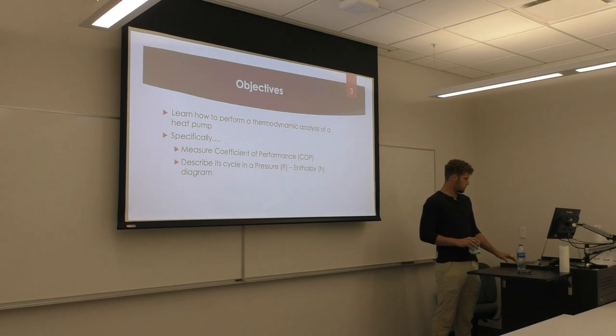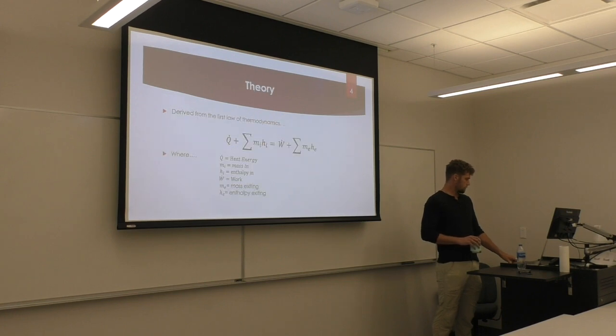The objectives would be to learn how to perform a thermodynamic analysis of a heat pump, because we all remember thermo, I'm sure, and loved it. Specifically, we want to measure the COP, the coefficient of performance, and describe its cycle in a pressure and enthalpy chart. We have some basic theories.